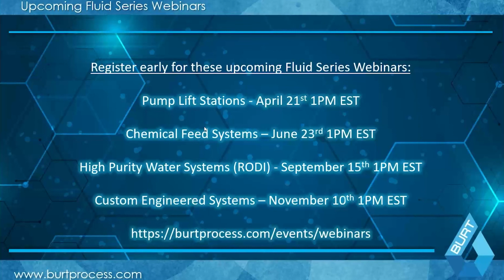The recirc pump is basically drawing off of the tank and recirculating it into an eductor, which magnifies that flow rate. But really it's just carrying my reagents under pressure and then educting it into the mixer. So there isn't necessarily a critical amount of sizing required for that recirculation pump in that situation.